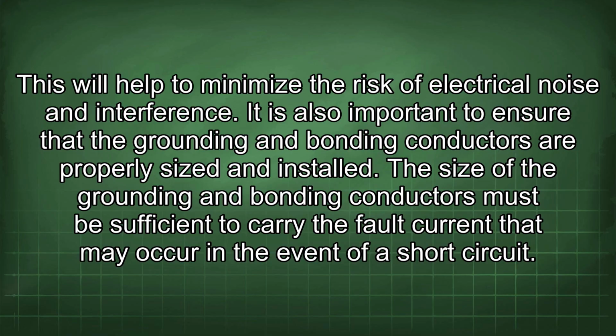It is also important to ensure that the grounding and bonding conductors are properly sized and installed. The size of the grounding and bonding conductors must be sufficient to carry the fault current that may occur in the event of a short circuit.